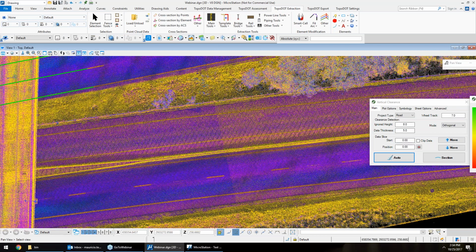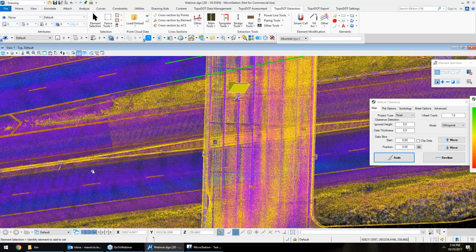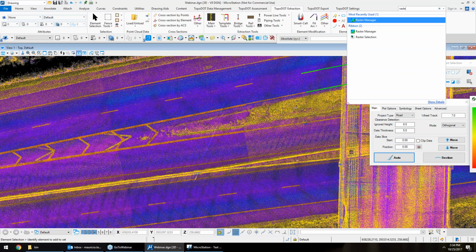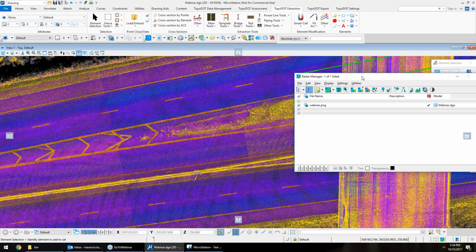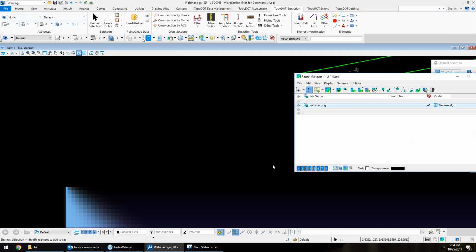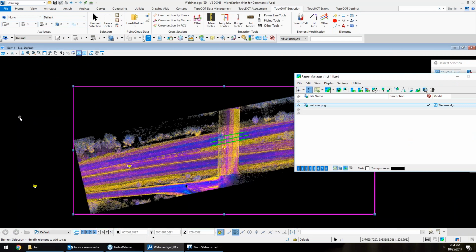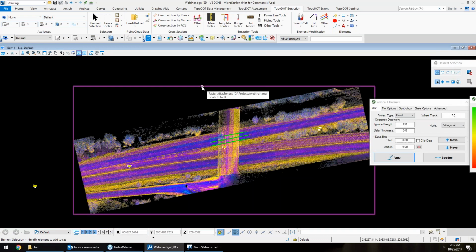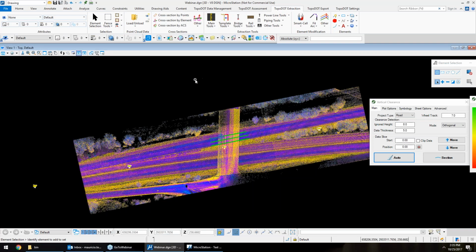We wish they would, but your engineers or somebody just might want to say, okay, I have this great data. There's all your line work. If they just want to know how it matches up to some design they have, you can extract all the lines and show them the lines, or you can just make these ortho images and send it to them and say, here, open up the rasters, see how things line up. It can save you a lot of work with trying to extract when maybe you don't really have to. Okay.